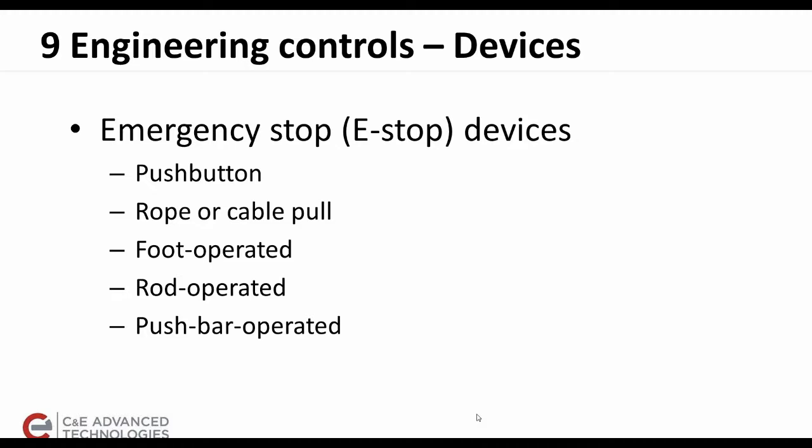Additionally, as I indicated, we've now included emergency stop devices with the other, now called engineering controls. Here's a typical example of where the general clause and then the specific clause comes in very handy. All of these devices, as far as the functionality of the controls goes, the requirement for a detent and so on, are all pretty much common to the e-stop devices.